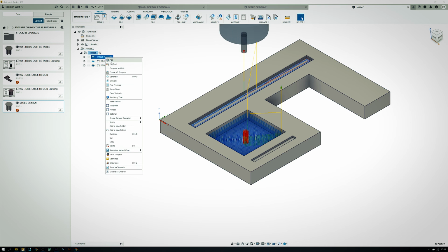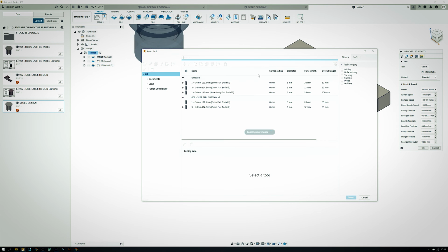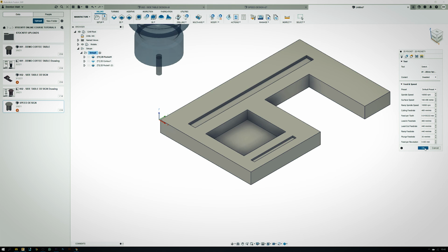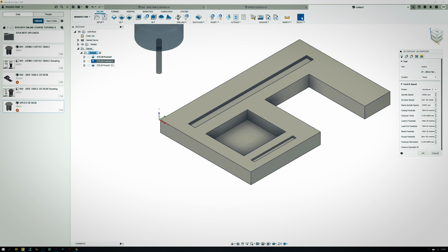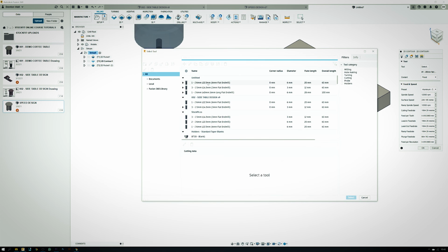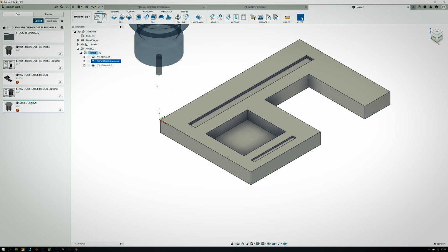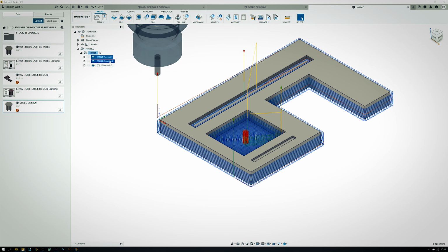It's important to make sure that you select the same tool and not have different tools selected, because that will cause a little bit of a glitch. Obviously, you want to make sure that you've got tool 1, 6mm. It must be the same router bit on those parts.